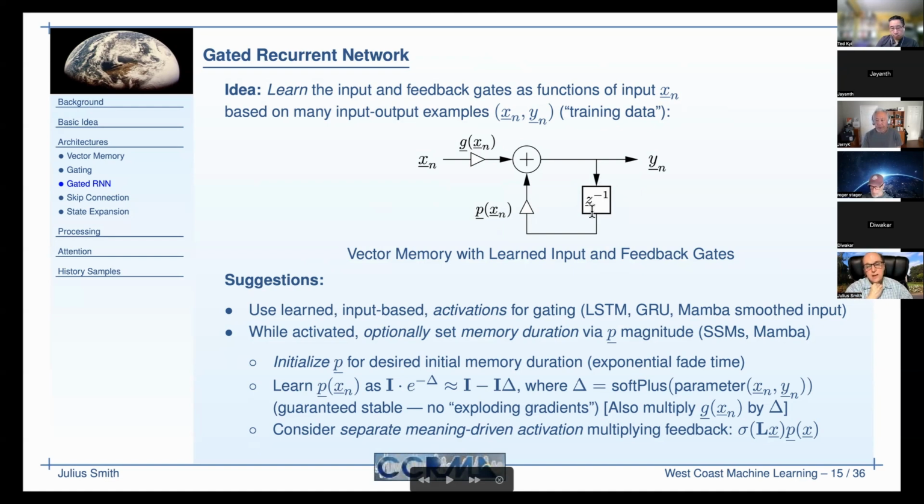Well, that sounds like a translation of the z-plane, and things like that are done. So z inverse just stands for a unit delay in this system world. It's the z transform of a unit delay. The z transform of a one sample delay is z inverse.